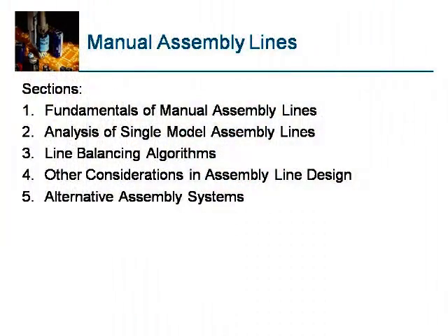First manual assembly comes, then automated assembly comes, because in the manual assembly systems we need to know what is called line balancing, how to do the line balancing, and what design aspects need to be considered in line balancing. Once you know these things, the automated assembly systems can be easily extended. Thus, let us devote this class exclusively to manual assembly lines.